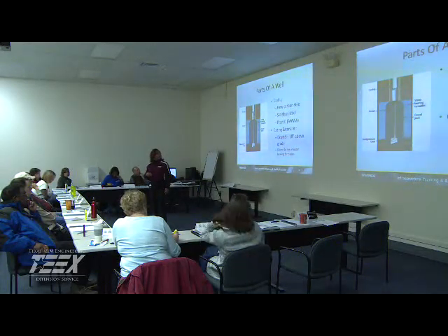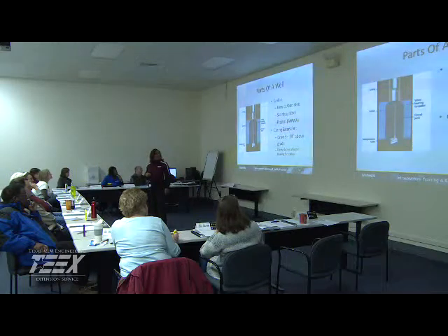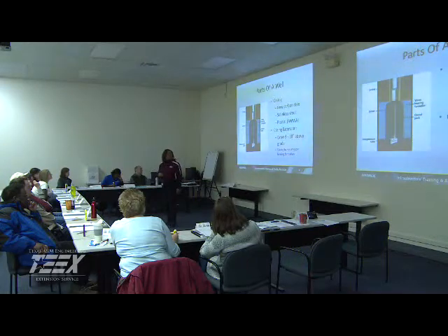We have the screen itself. Now, the purpose of the screen is to reduce the amount of sand being pumped, and then you have the gravel pack outside that screen. Also, the purpose again is for the reduction of that sand. The screen is wider than the pipe pumping.